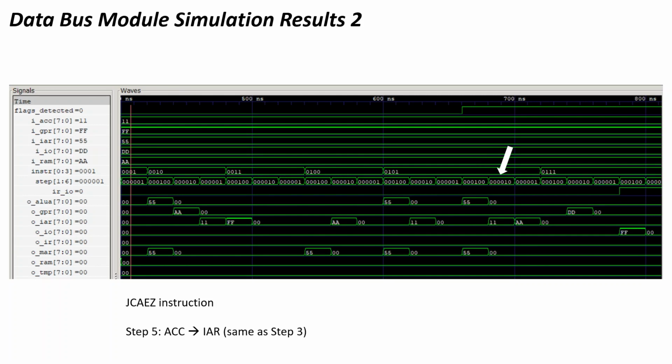We'll set up to jump, and then for step 6, we'll actually jump by taking the address from RAM and putting it in the instruction address register. The last operation is the IO instruction. This has the IR_IO signal, which signifies it's an input operation.